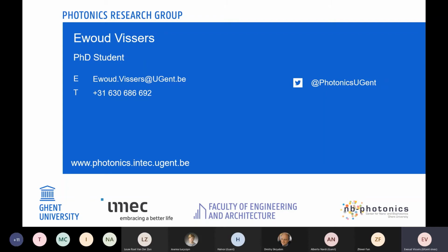When that is done, I take my sample and on a spin coater, I spin coat SU8. And since SU8 is a photoresist, I then directly expose my waveguides into the photoresist. If I then develop and bake, the photoresist will stay there, and that will be my waveguide.